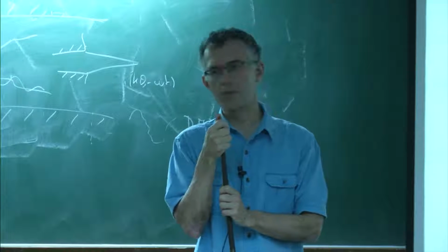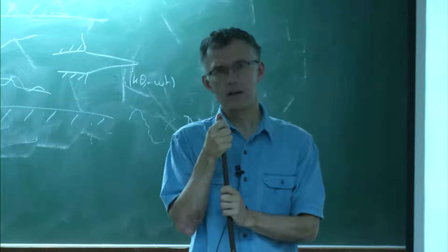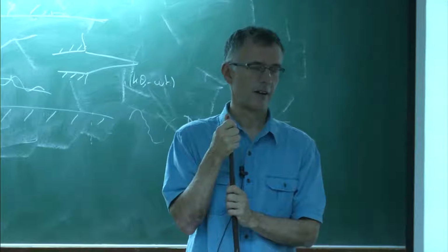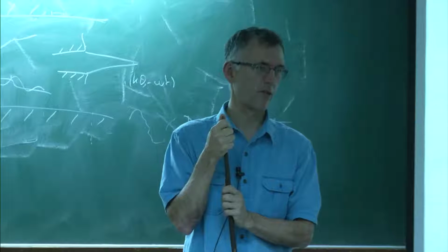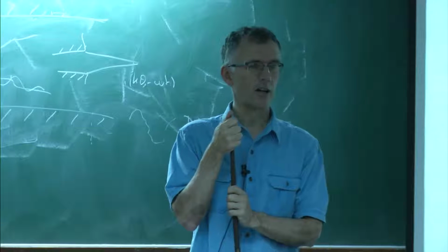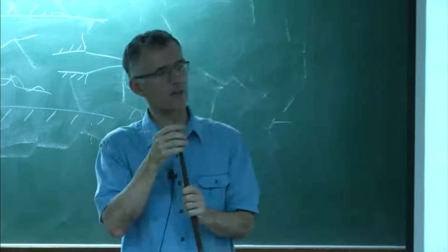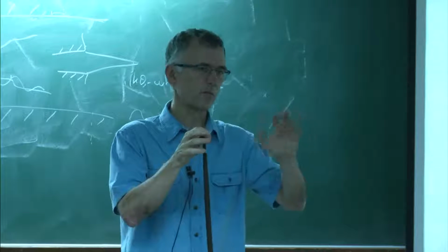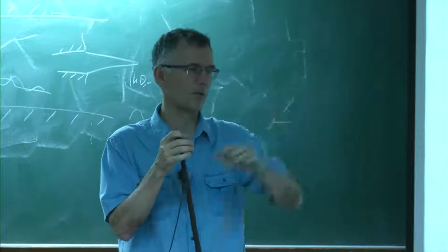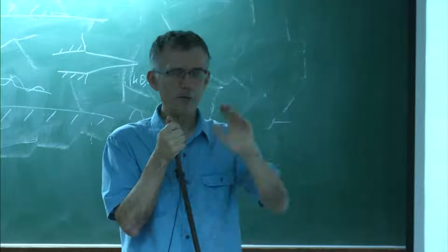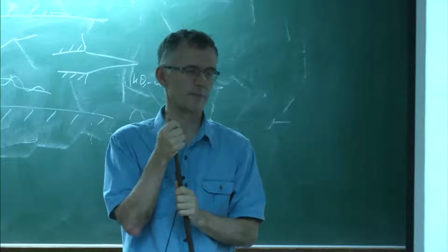Well, for soot, it's true, but there are some. If you give me the soot volume fraction, I can have a reasonable model for soot emission. If you have the volume fraction, going to the radiative flux is not as difficult. The people working on radiation have some models for that. The weak part is to get the volume fraction. But if we have it, we have some crude models to do it.